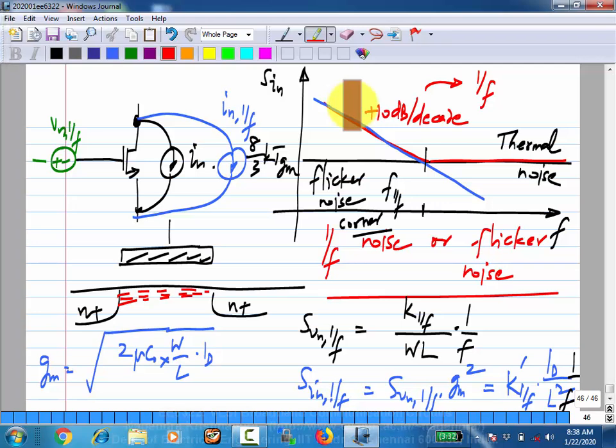And also one good thing for us with serial links, as long as we are dealing with very broadband circuits, I said our focus is on making very high speed links, where we are talking about frequencies of gigahertz and so on. So flicker noise is less of a concern. If you are focusing on audio and instrumentation and things like that, it is a really big concern. Because we will be operating usually at frequencies that are well beyond the flicker noise corner, and thermal noise is the dominant noise in our case.